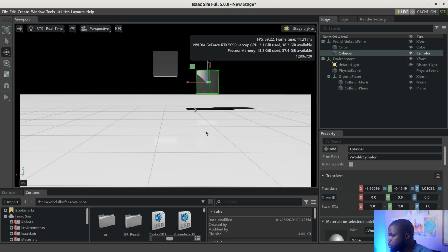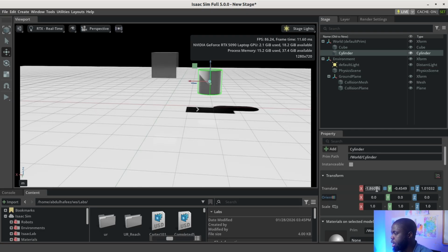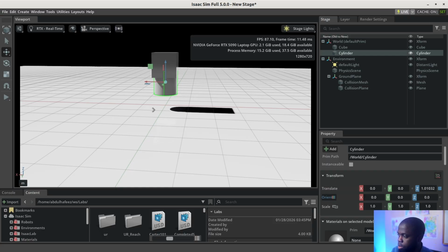And if I just want to position it on the floor, and I don't want to move it because it's maybe a little bit difficult, I'm going to come to X over here inside this text box. I'm going to click on Control and come inside and put 0 there, and I'm going to come to Y and put 0, and I'm going to come to Z and put 0. So now you're not going to see it fall because it's going to see it as the middle point of the object.